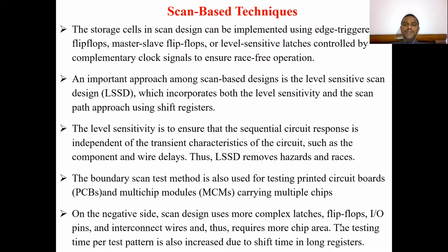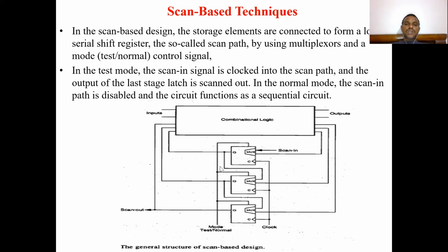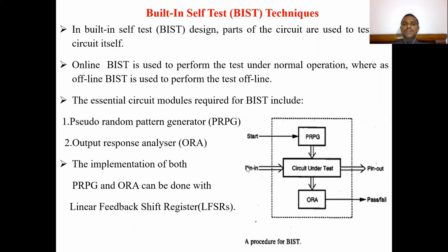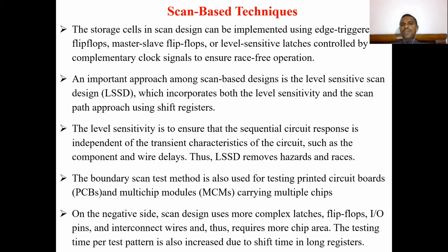At the same time, the testing time for test patterns also increases due to the shift time in long registers. We are considering serial shift registers here, so the test time increases. If you use parallel registers, we can reduce the test time. So this is about scan-based techniques and ad hoc techniques.